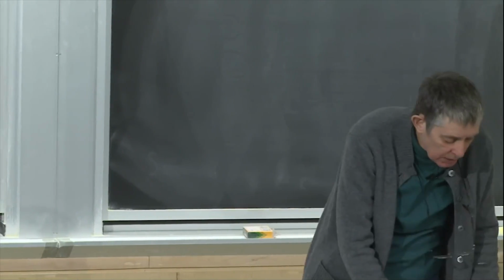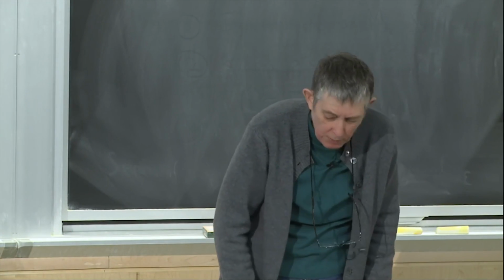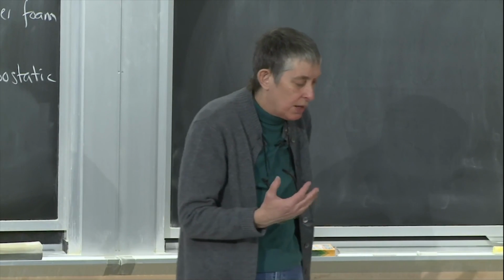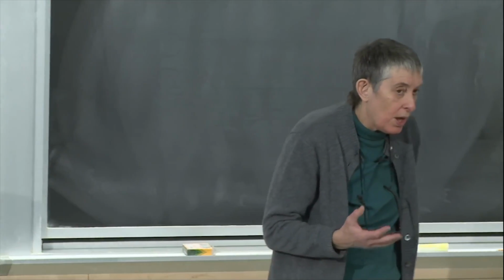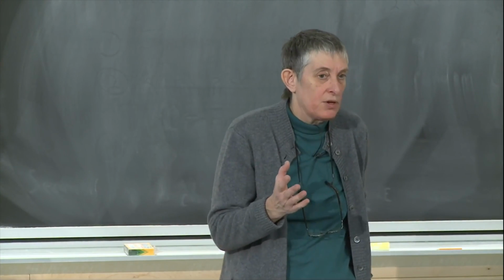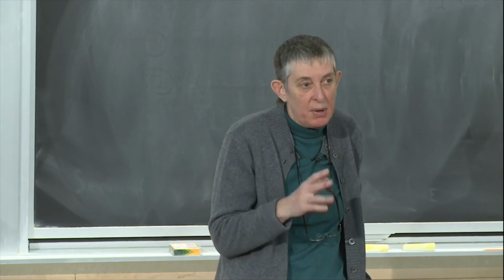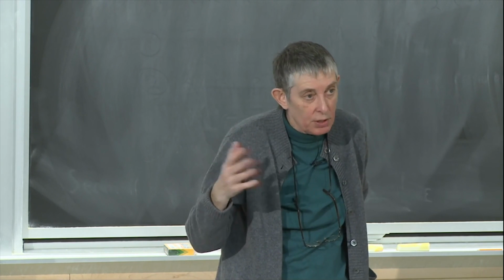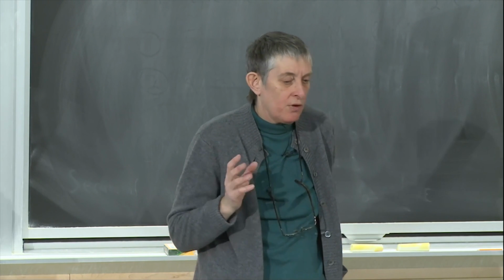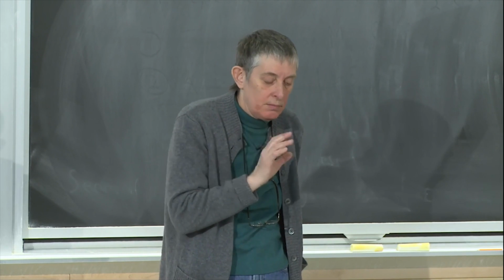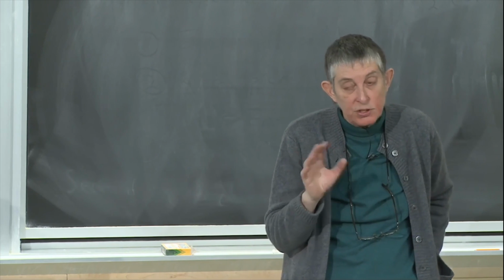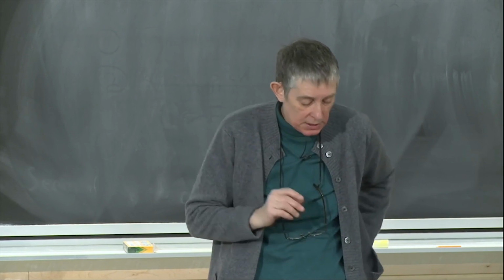Okay, well, let me talk a little bit about the lattice materials too and how we make those. We're going to start talking about the modeling of honeycombs and foams. And when we do that, we're going to see that if we have a structure that deforms by bending, the properties vary with the amount of material in a certain way. But if we have materials where the deformation is controlled by axial deformation, the stiffness and the strength are going to be higher at the same density.